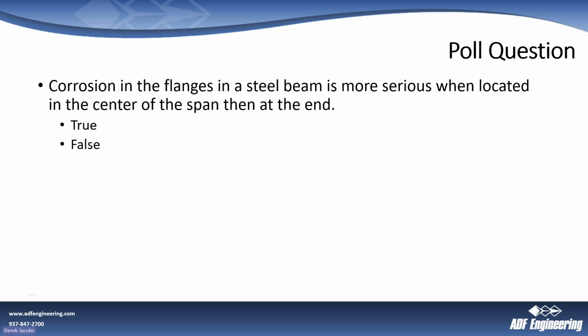All right, so a quick poll question. You can think about it in your mind. I'll give you half a second, but corrosion in the flanges of a steel beam is more serious when located in the center of the span than at the end. Is that true or false? You guys just think about it. I'll give you half a beat. And so that is true. Good. We want to make sure that we're watching for the repairs where the stress is the highest.